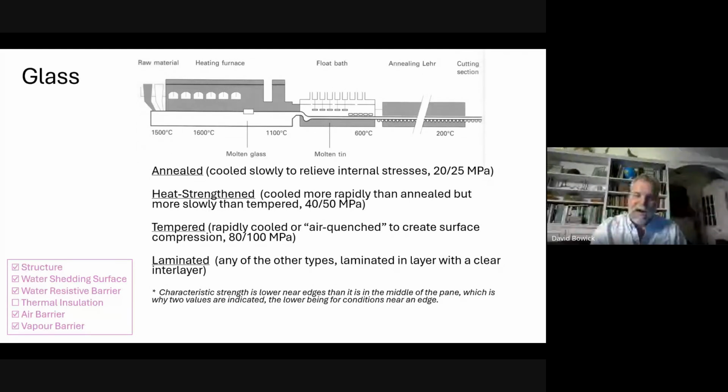Glass fiber has an extremely high strength, like 1,000 MPa, 3 times as much as steel. Very, very strong stuff. The trouble with glass is that if there is any little imperfection, a crack can begin to propagate to the point where it will fail completely, at a stress much lower than the strength of the material.